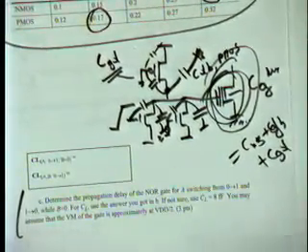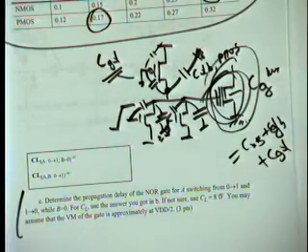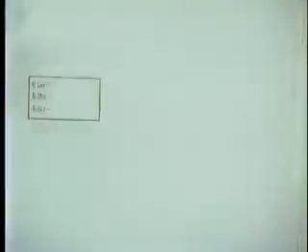Okay? And now the last part is very easy. I say, okay, now you have the capacitor, you have the resistor, compute me the propagation delay. It's 0.69 times RC. So you're basically done, right? Once you have the capacitor and the resistance, you're basically finished.